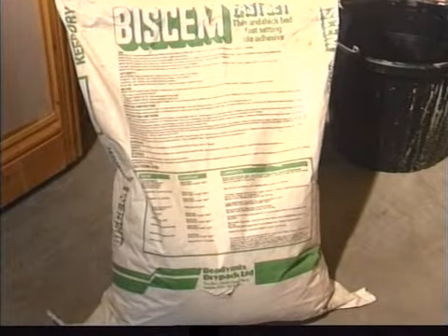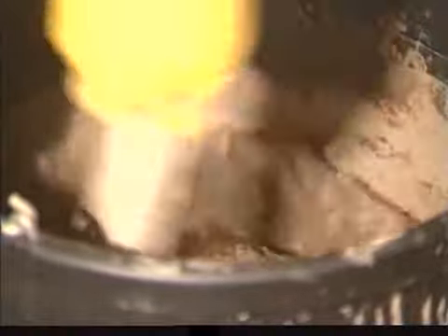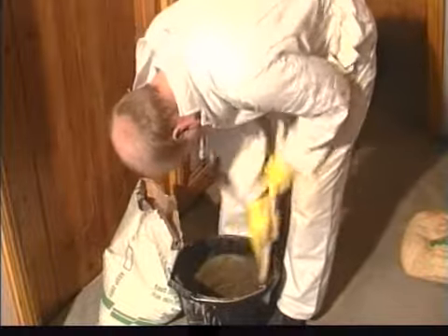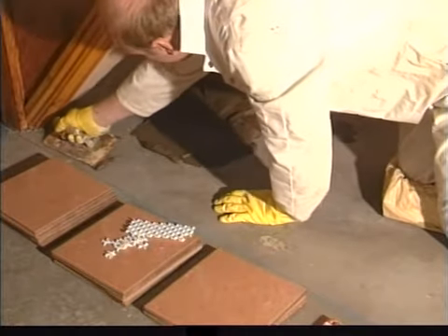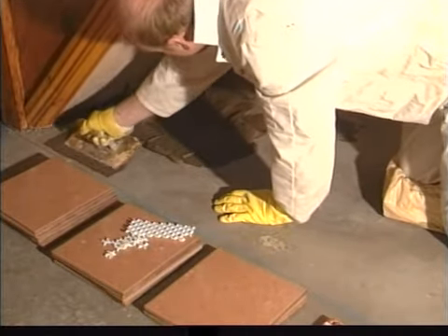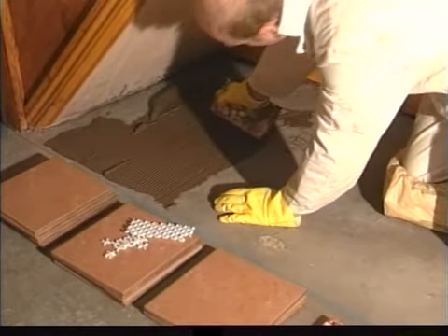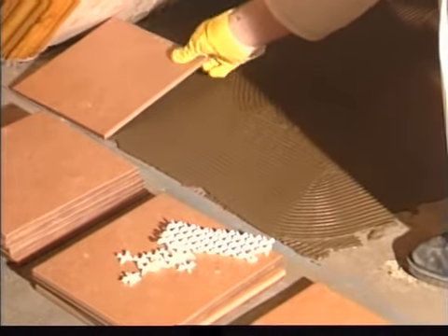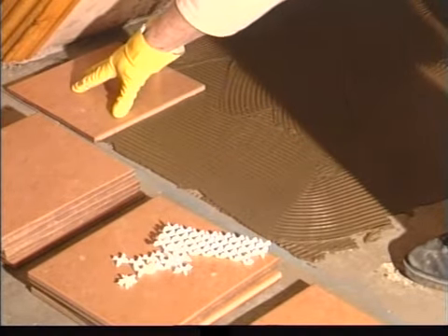Whereas wall tile adhesive is usually pre-mixed, floor tile adhesive generally comes in powder form and needs to be mixed with water. Follow the maker's instructions. Spread the adhesive from the center line towards the outside walls. Only attempt to lay a small area at any one time. Make sure the tiles are firmly bedded into the adhesive. Continue to lay down along the center line, spacing as required.